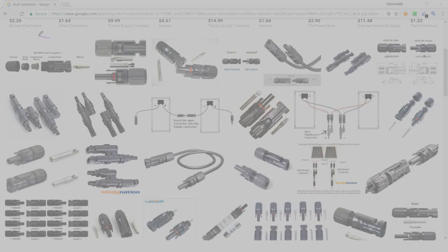You run a conductor through the end of this and into this metal housing, and then you crimp the housing, and you have to snap it into this conductor, and then this piece twists and kind of rotates, and you have to make it up tight, otherwise it doesn't connect the cable to the pin. And so when you're making up the MC4 connector in the field, there's a number of spots that can go wrong.